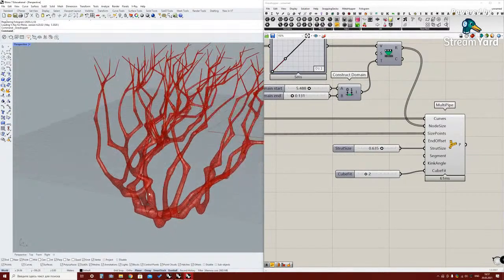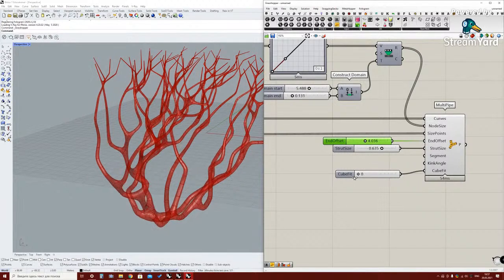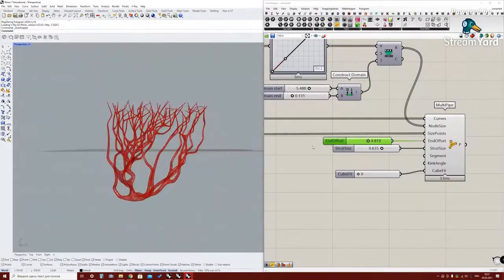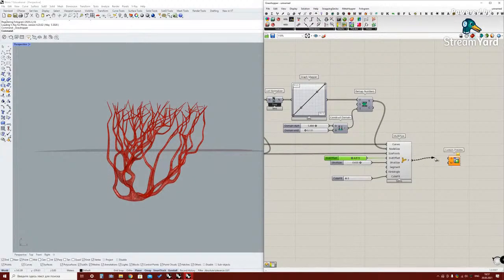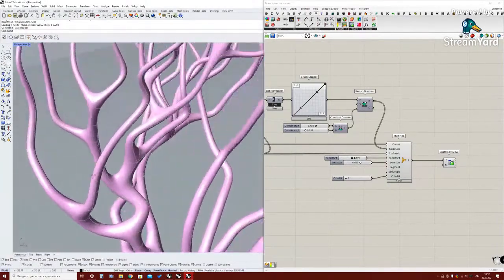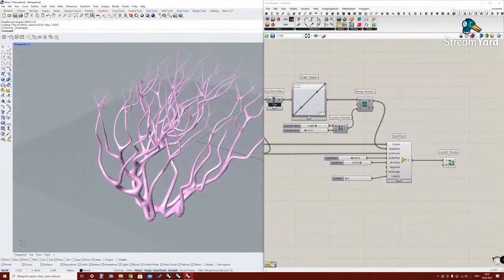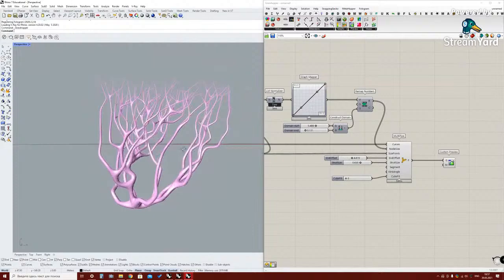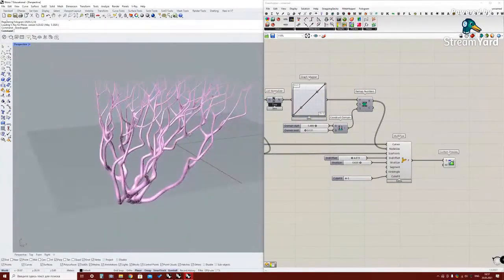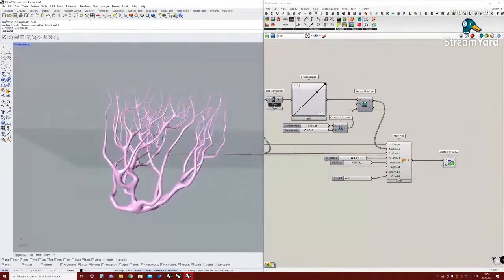And also we can work a bit with end offset. Let's see. The end offset. Maybe also works for us. Let's preview it using custom preview. We are not going to add any creases here because the topology of this SubD is not perfect. And you can put creases only where you know that you have proper mesh strips and you know the mesh face directions. Here it is more or less random, so we're not going to do it.